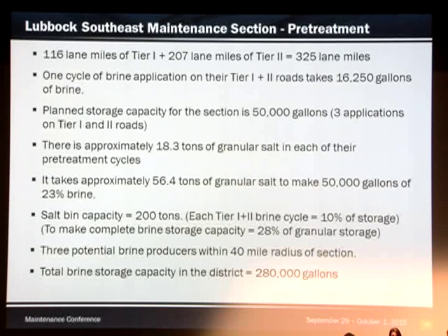We've talked a lot about the concept that you make your brine beforehand, and you've got it sitting out there, and when it comes time, the storm's on its way, you get out there and shoot it. And that's great. That's what should happen. The problem you run into is when you've got a long duration storm, or multiple storms coming in back to back. When you shoot all your brine in pre-treating and you don't have good weather to make more, you're going to be out there making it in bad weather if you don't have a producer to order it from.